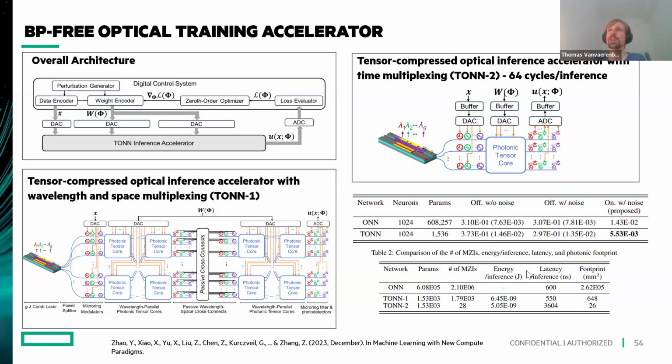In addition, at some point, if you go to very big systems, there might actually be latency that you want to avoid. Also, if you go off chip, you will have some power penalties because you need die-to-die communication. So even though the initial idea might be that the crossbar itself is passive, has low loss, and so you might be safe, as soon as you hit the boundary of what you can do in a chip and you need to talk to the outside world, you will hit penalties again. The overall picture might be more complicated than just ignoring it, so I would be very careful about it. I think that's one of the reasons we in photonics should keep caring about area as a metric. Yeah, that's my take on that.